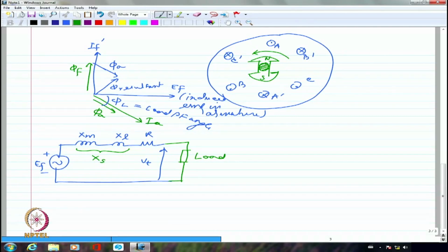In the case of a synchronous machine, because your synchronous reactance is the magnetizing reactance plus the leakage together, I am going to have a very large value. It can be greater than 100% sometimes. So you are going to have a very large value as synchronous reactance, which tells me when I calculate regulation, eventually the drop could be pretty large.